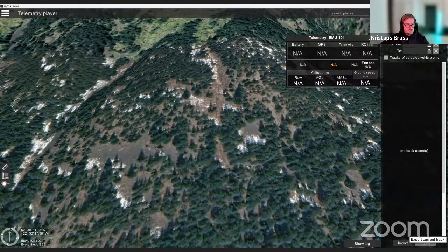If I'm not mistaken, you can export it to a CSV file, but I believe one option was also KML. This means you can do a flight, and then that KML file you are able to import back into UgCS as a route. Later, if you have some time, I can also show this to you. But the idea is simple. You do a flight manually while the drone is connected to UgCS.